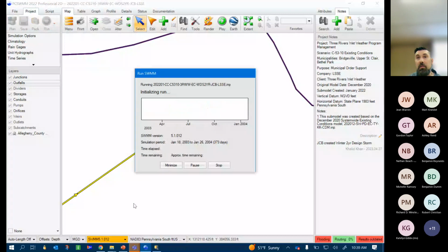Because we're using a hot start in this model run, and that comes standard, if I were to change one of the modeling elements, I believe we would get an error saying incompatible hot start file, something to that degree, and you would have to rerun it. I highly recommend that anytime you change any element or any representation, a new hot start file is created and used for your simulation.